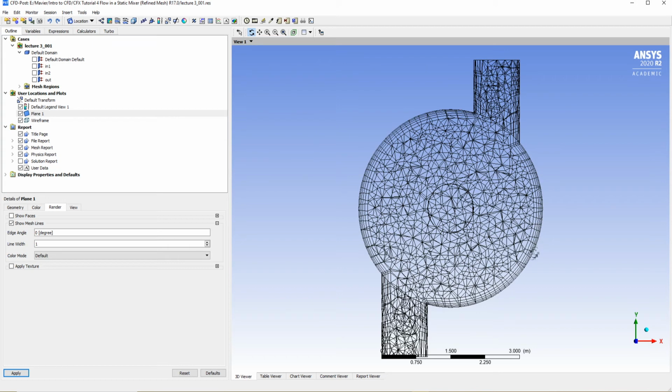Better organized elements in the border give us better results at the regions near the walls. If you guys remember from fluid mechanics, as the fluid gets closer and closer to the wall, its velocity tends to go to zero due to the no slip condition, where the fluid assumes the same velocity as the wall.